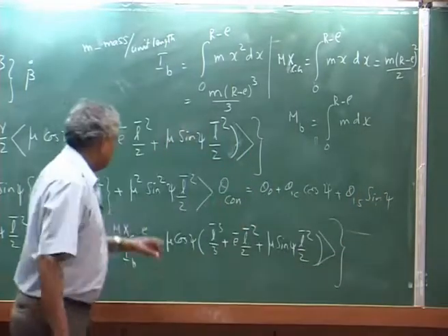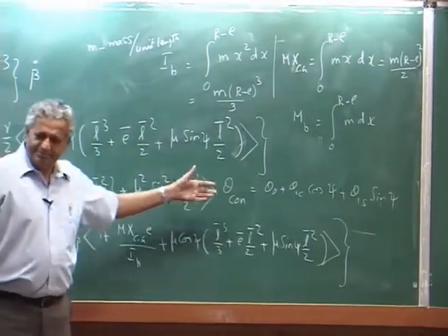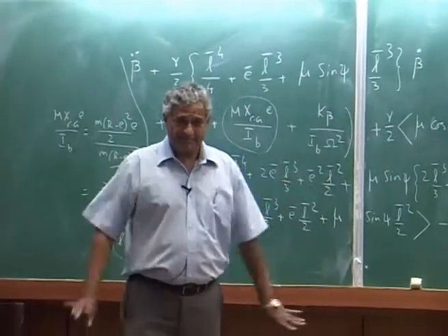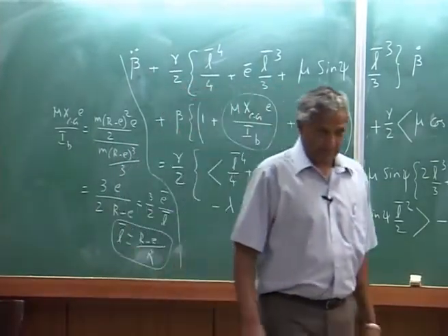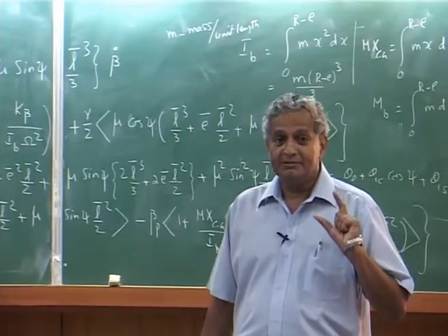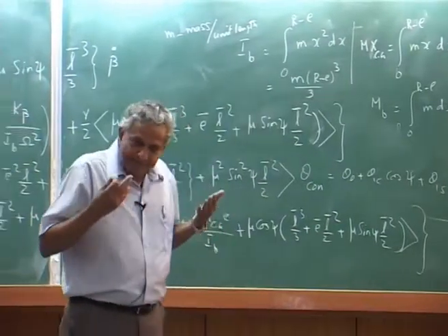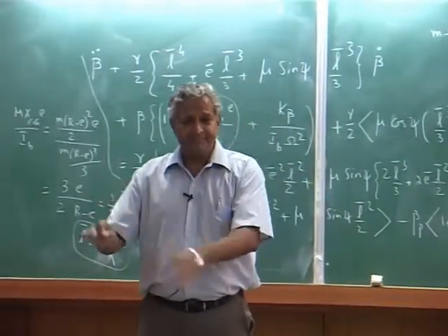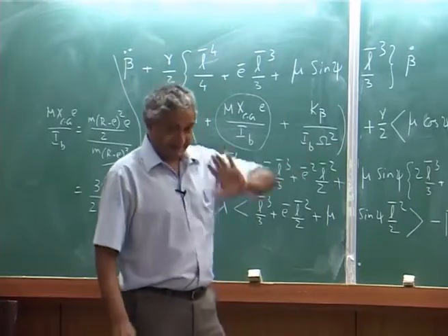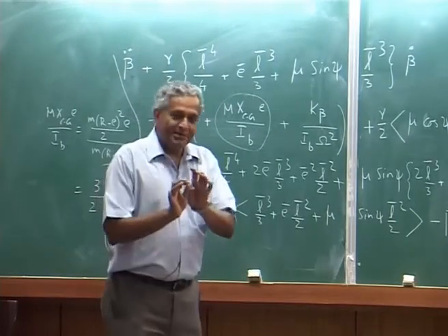You have already second harmonic, this gets multiplied, third harmonic, all the harmonics can come. So, when you neglect everything, I take only first harmonic, but that is not correct, because as you go to high speed, you will find slowly second harmonic will dominate over the first harmonic. But this is the assumption we make, we neglect it, and our results will be wrong, but it is okay, I am getting some trend. Otherwise you have to take the full thing.